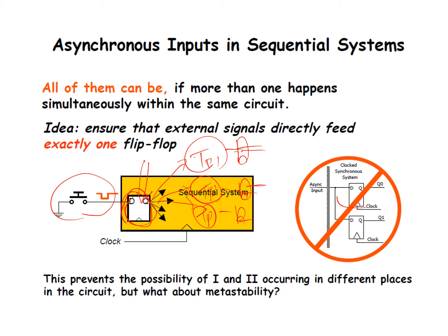If you have multiple flip-flops at the input, this makes the situation even worse, right? One of those may fail, and any one of those may catch the value one cycle early or late. The timing is all messed up, right? So we prefer to have only a single flip-flop at the interface to make sure the timing is consistent for all the paths.